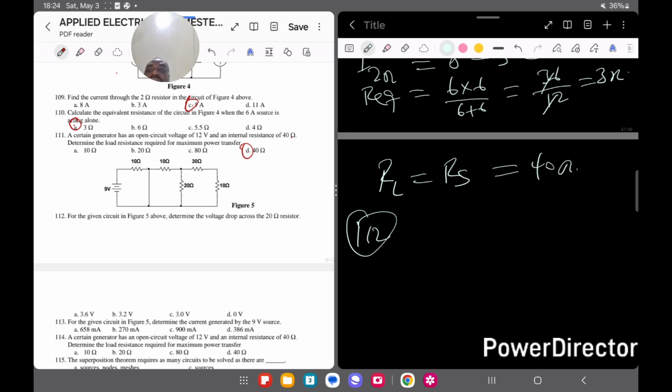Because we know that if you have resistors in parallel, and then you connect a wire in parallel with those resistors, because the wire has a lower resistance compared to the other resistors, all the current is going to pass through that wire. So that means the current flow in the other resistors is almost 0. So it's the same concept here.